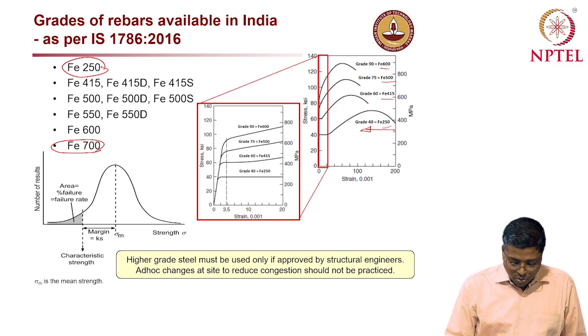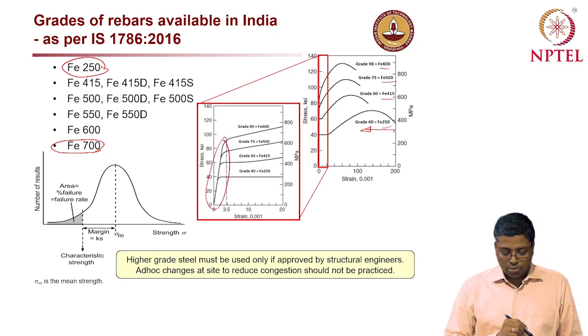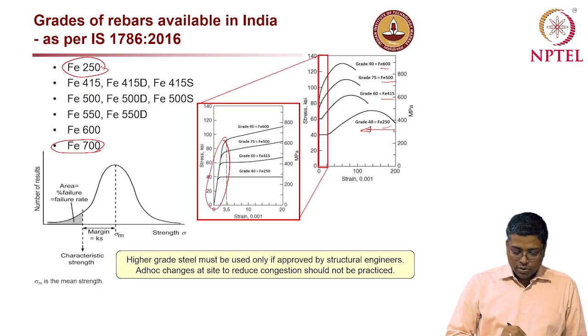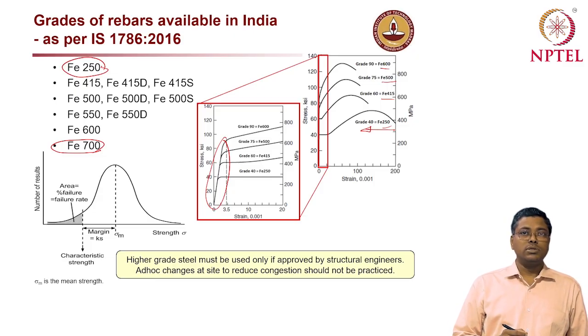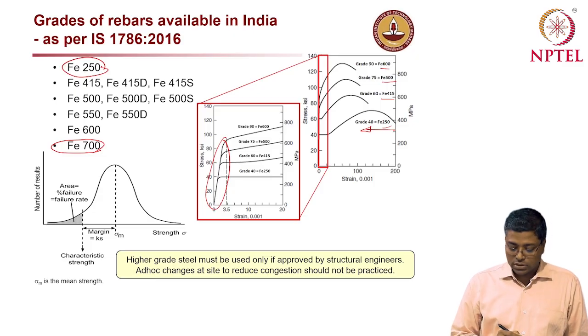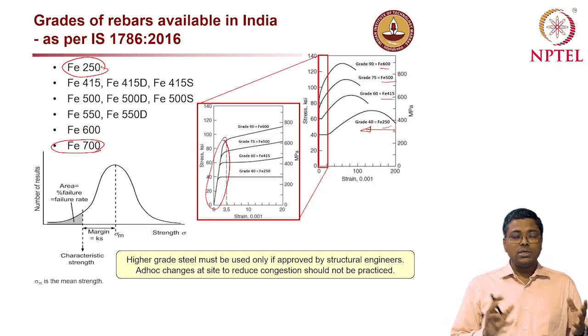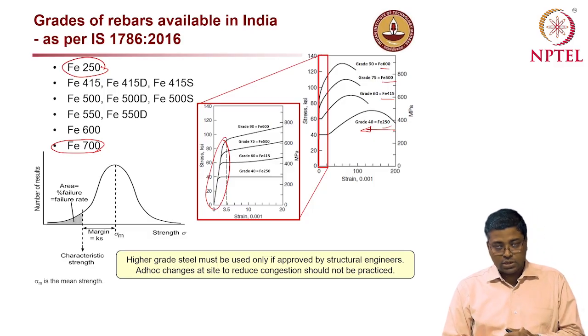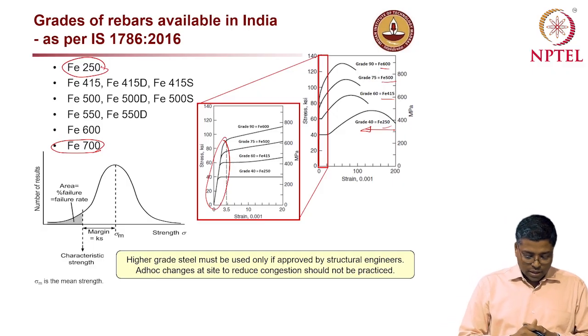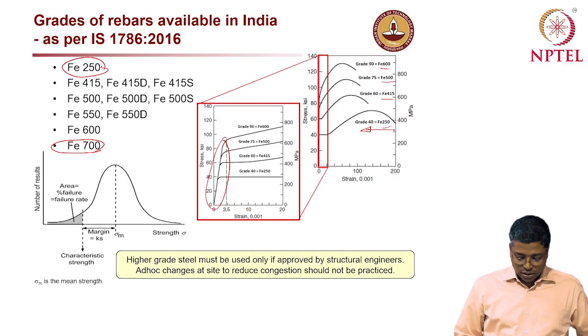And if you look at the modulus of elasticity, you see that pretty much all the steels have similar modulus of elasticity, so that is maintained. But definitely ductility is a problem, especially when we talk about durable structures and earthquake resistant structures. Ductility is very, very important. So the structural system, when we talk about steel concrete system, should still be ductile enough. So the structural engineers have to take care of that part.